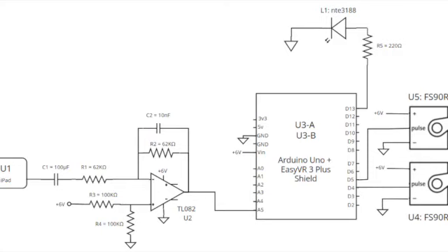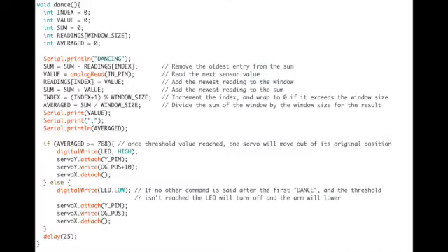Because Arduino contains a 10-bit analog to digital converter, this signal was mapped to a value between 0 and 1023. Because our filter was a first-order low-pass filter, the cutoff frequency was not sharp enough to completely attenuate the frequencies above 250 Hz. To do justice to the base frequencies, we determined a proper threshold value. And because most songs have frequencies that are between high and low, we decided to create a running average filter with a window size of 3 readings to get an average waveform of the digitized signal.